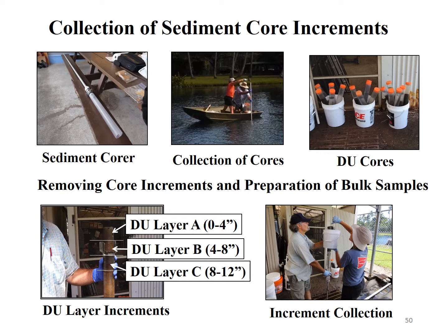Typically, with these commercial devices, this pond at high water was about 12 feet deep. So typically there are commercial coring devices that you can employ in waters easily up to about 15 to 20 feet deep. Once it gets deeper, then we're looking at different challenges and different tools, and obviously as you get deeper, it's potentially costlier, slower, more time consuming to collect cores in a given decision unit. We'd still be using the same principles applying to sediment in deeper water.